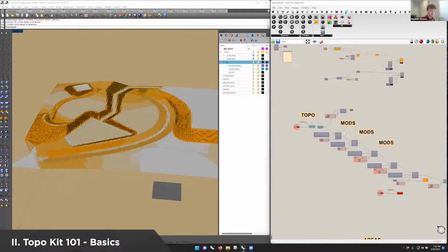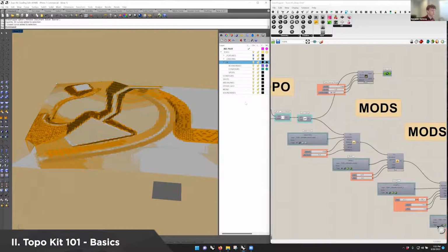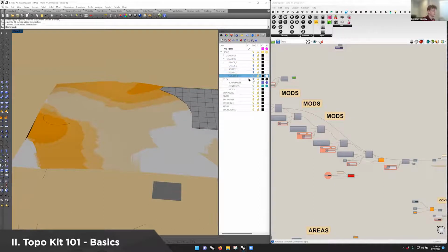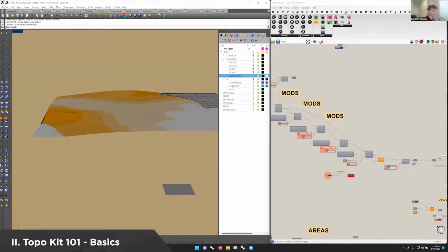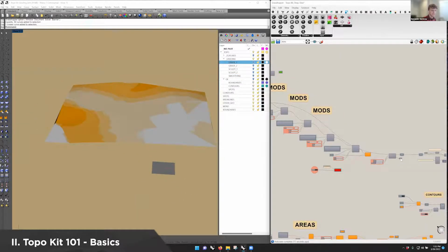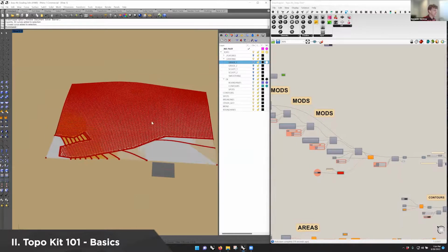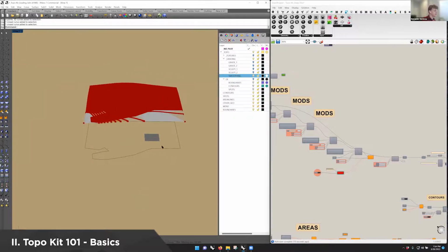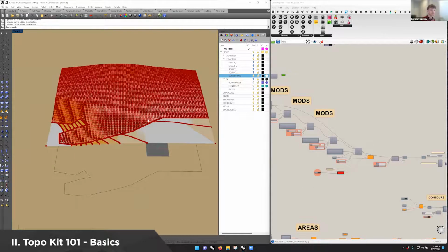And if you're in the Grasshopper file and you want to follow along, I'm going to show step-by-step how we're building this topography. And I'll show it by plugging these in individually and turning on the layers that are applicable. So right here, the first thing that we have is smoothing. Essentially what it does is it takes your surface and a defined boundary, which we have defined as this unusual shape here. And you can literally see where it's adding extra points to increase the definition of your mesh to allow you to manipulate it more specifically and intricately.